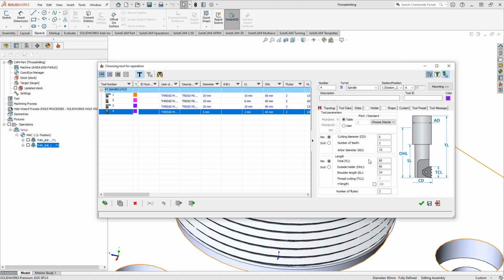So just for everybody that doesn't know, the tapered ones are for the national pipe taps, or the BSP, which is British pipe tap, as well as the straight threads are for all your straight threads. Yeah. I think normally you'll find it in the piping industry where they have that taper thread just because of the unique way that those things have to affix to each other. But yeah, it's British pipe thread and national pipe thread. National pipe thread is basically North American.